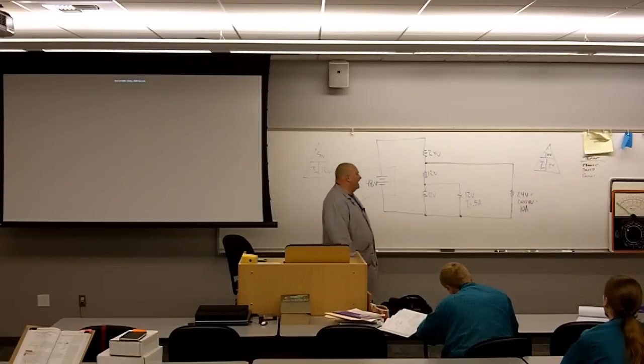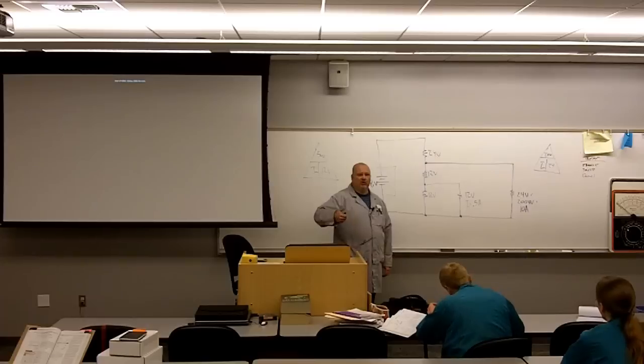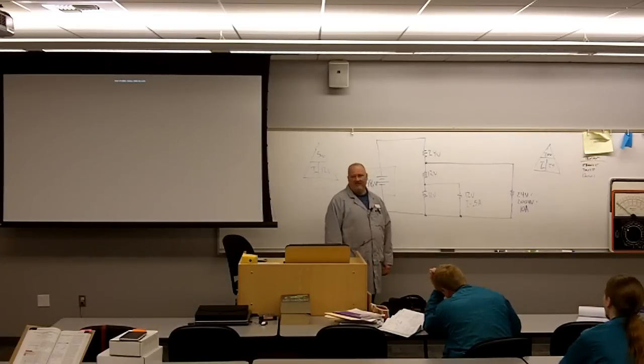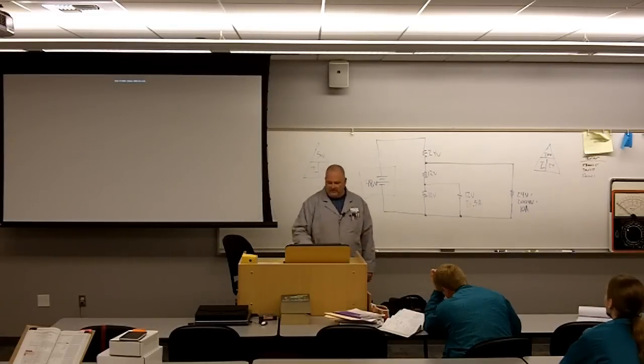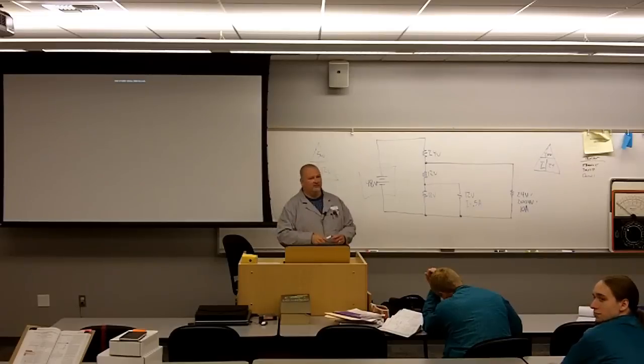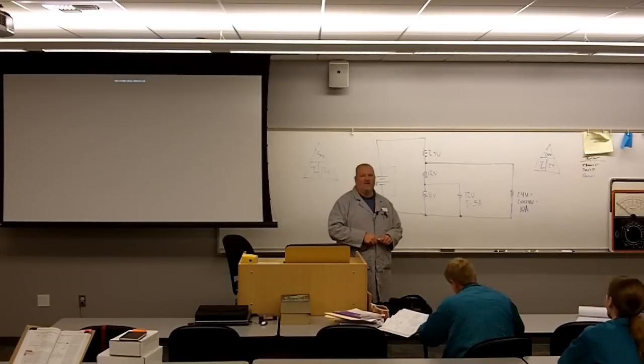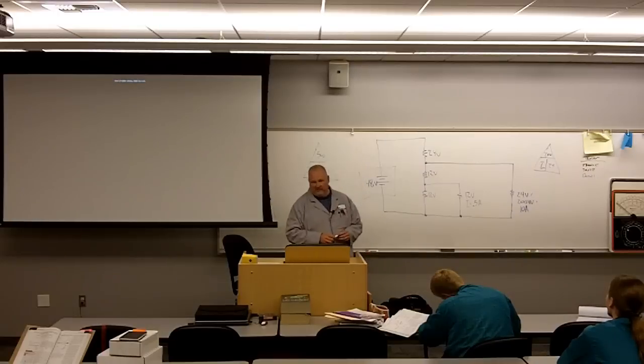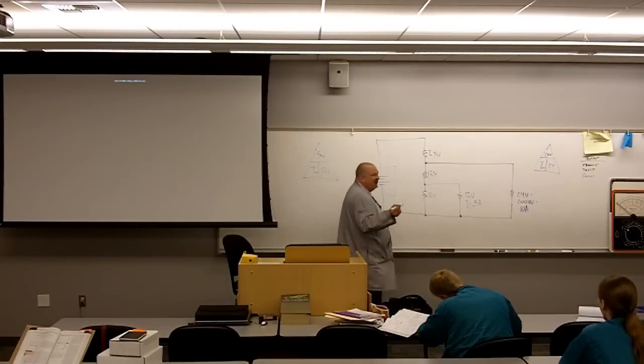Okay. So I said the thumb rule is that the bleeder current is 1/10 of the total load current. What's 1/10 of 10.5? 10.5 divided by 10 is 1.05 amps. Do you all agree with that? Getting some puzzled looks. 1/10 of my total load: 1/10 of 10.5 is 1.05. Agree with that? So that's how much current.